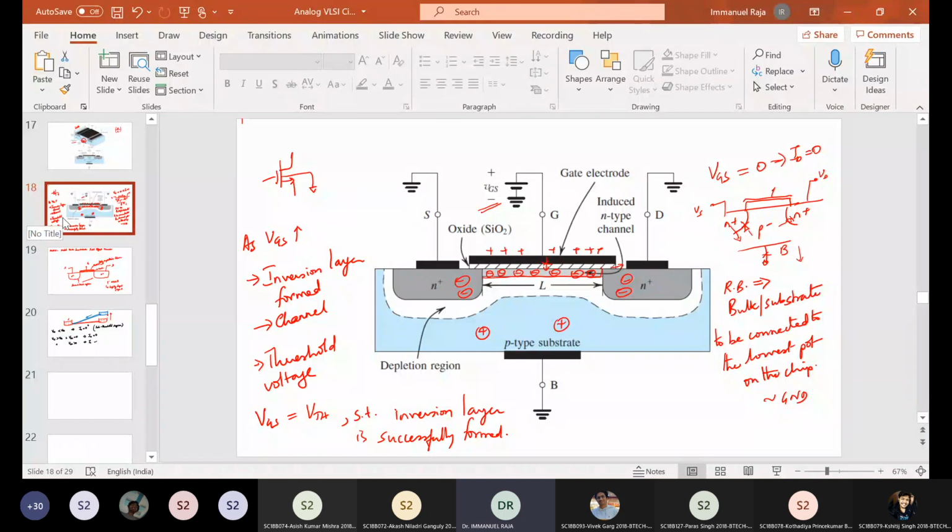In any commercial fab, in any commercial CMOS technology, the source and the drains are equally doped. You might have studied it in the fabrication course. All these N plus regions go through the same mask, so the silicon will have a mask where this region is opened out, and this region is opened out, and you have a uniform N plus deposition. Probably what you're asking is, because of deposition inaccuracy, maybe there's a slightly higher doping on one side than the other. Is that what you're asking?